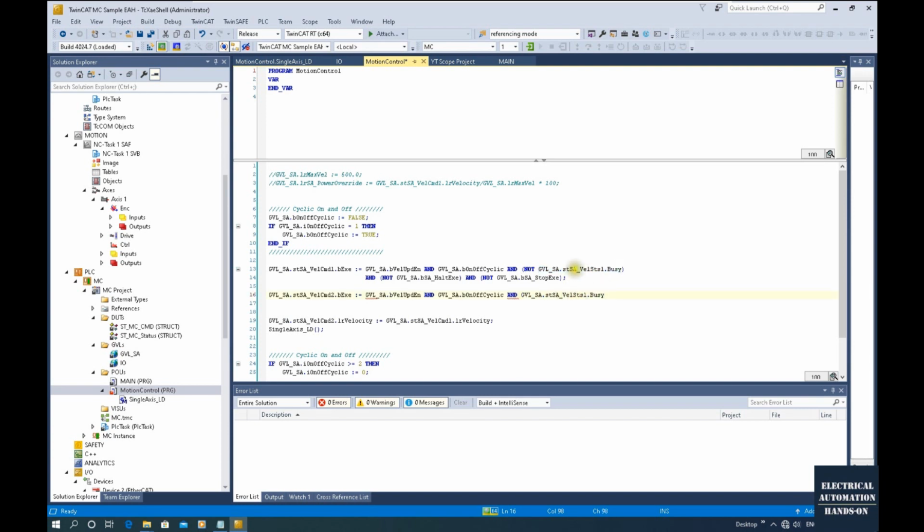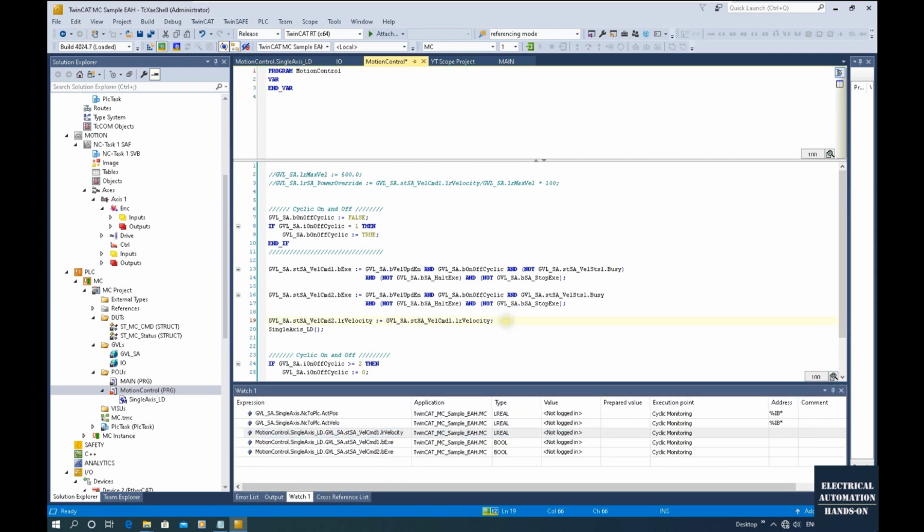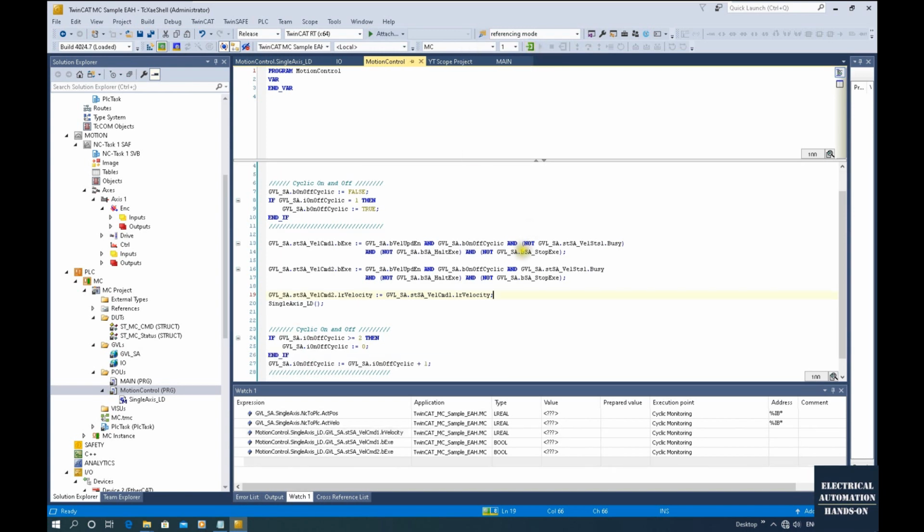So we will use busy directly. Okay, see this difference. So these two commands won't be turned on at the same time. This busy will control whether we go this way or this way. It won't be turned on at the same time. Okay, and for those halt and stop, the same idea. We'll use that here. Okay, copy to here. See this difference. And also these two speed commands for both function blocks are the same. So we will use this command 1 in this watch list here. Okay, so now let me log in the logic.